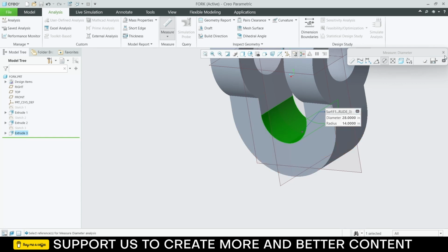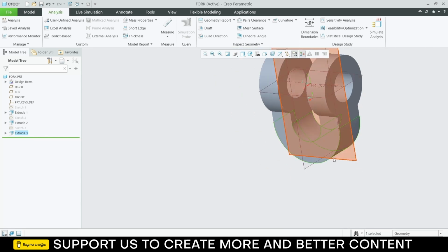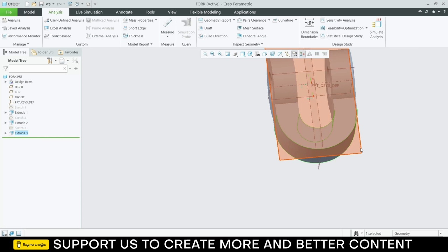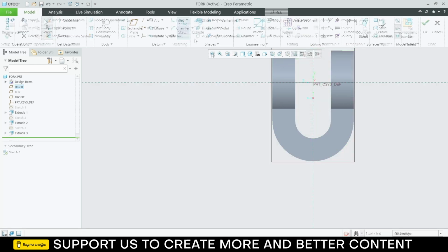Okay. So all the time, I'm taking it here in inches. Okay. Select this. Click normal to the screen. Click on sketch.